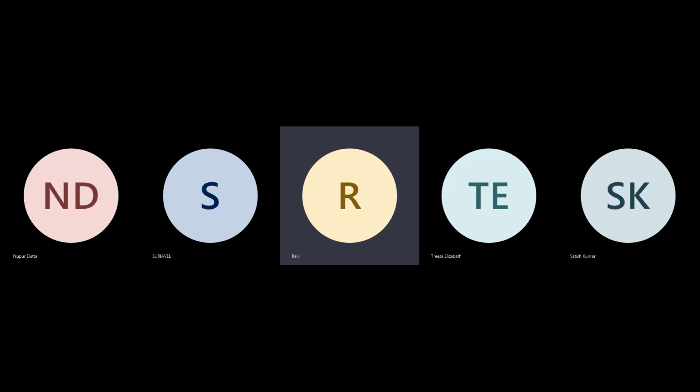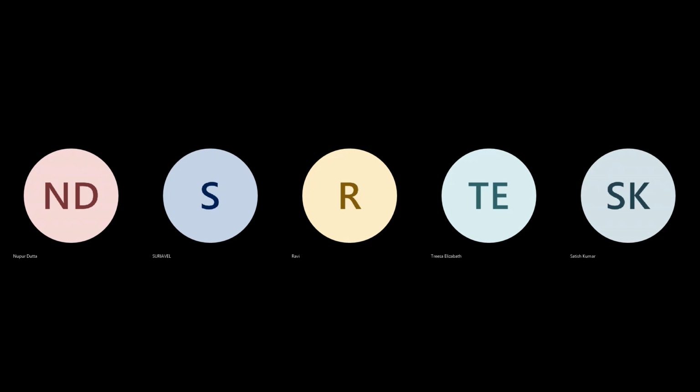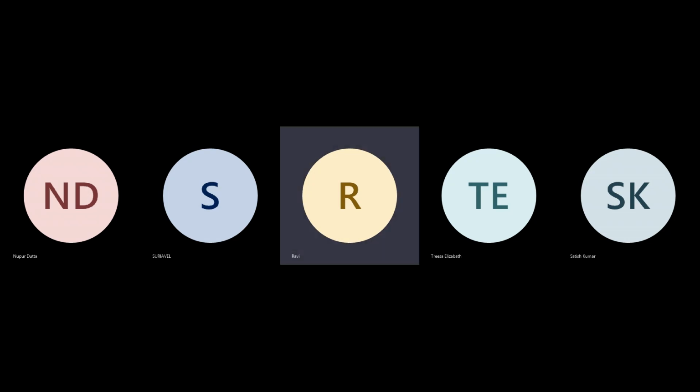Don't assume what you have got is a golden necklace. If, for example, at the floor plan stage, your timing is meeting and your utilization is in good shape, you don't have to worry about synthesis. Your tool is doing a good enough job for you. If there are problems, if you are seeing growth, then you go back and give the feedback.